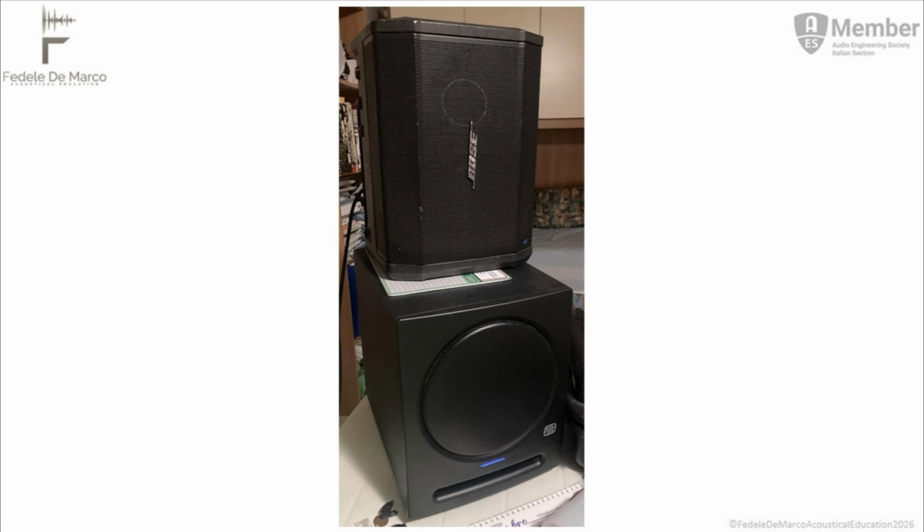This is the usual setup that is going to be measured and aligned, well known as the protagonist of all my recent videos. It is already known that the top is delayed by default by 20 milliseconds to allow for easy data reading, and that for a correct alignment, about 20.5 to 21 milliseconds are needed, plus a polarity inversion.